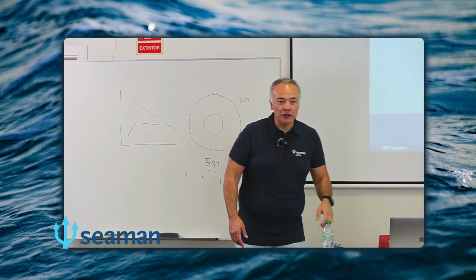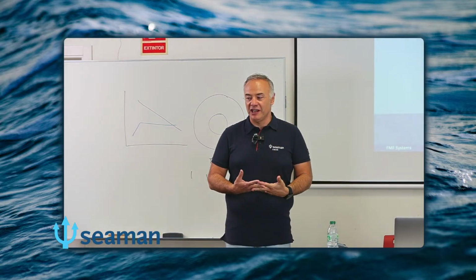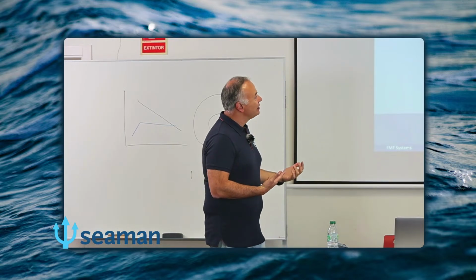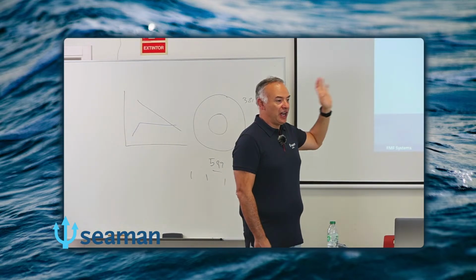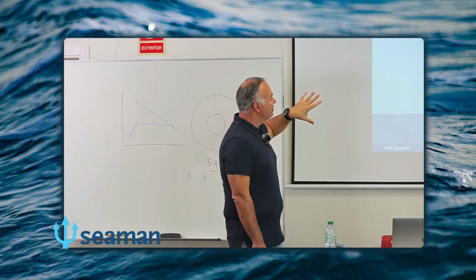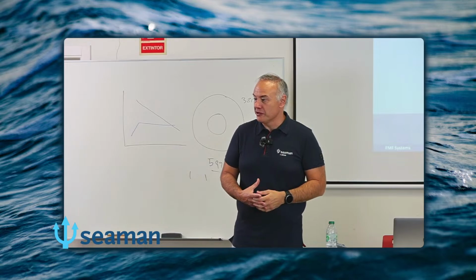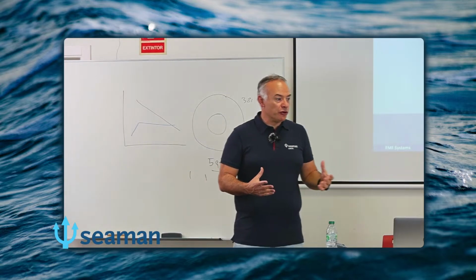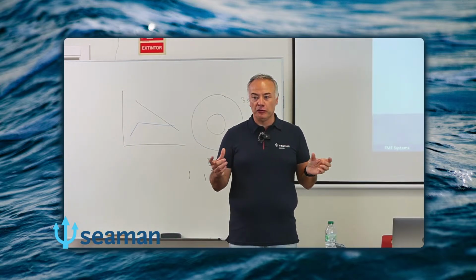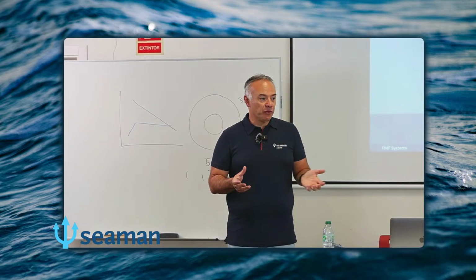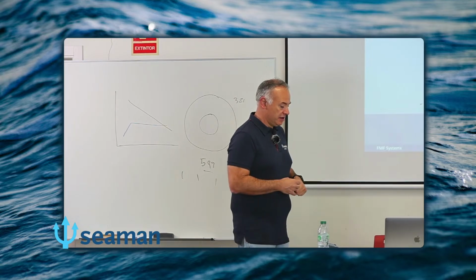So if you want to advise or recommend to a client a good equipment for size measurement of cod or saithe or haddock, then this will be a split beam sounder in a fixed low frequency, or in a range of low frequencies. There are some transducers now where the range is from 25 to 45 kilohertz in chirp mode, or maybe a single frequency at 38.